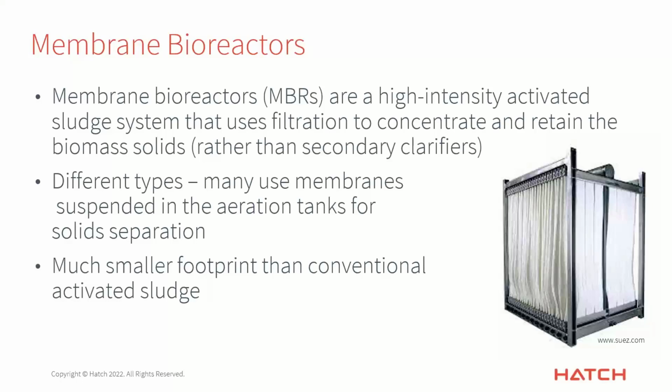So there are many different types of MBR systems, but some of the most common ones, like the one that we're showing here, that hollow fiber system, are arranged in cassettes, and very often they sit right in the bioreactor itself. And the idea is that you want to basically have them sitting right in the mix liquor, and then you filter, take a permeate out through the membrane surface, and you hold back all the solids, keep back all the good bugs that you want to keep, and get very low solids in your effluent, basically 0 solids coming out, and then your treated water will move on that way.